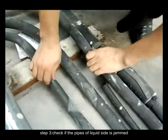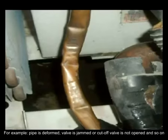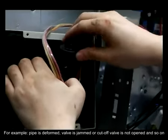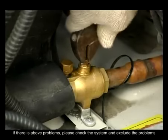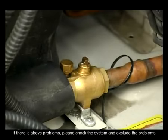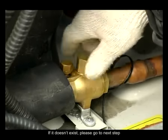Step 3. Check if the pipes of the liquid side are jammed. For example, the pipe is deformed, a valve is jammed, or the cutoff valve is not opened, and so on. If there are the above problems, please check the system and exclude the problems. If they don't exist, please go to the next step.